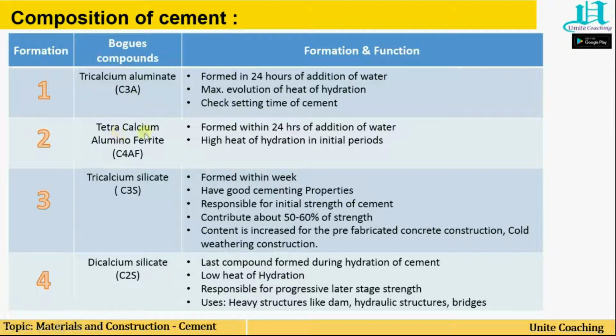Then what about tetracalcium aluminoferrite? See, it is the second compound to be formed in the cement, and it is formed within 24 hours of addition of water. And high heat of hydration is generated in the initial period because of this. Because of C4AF, high heat of hydration is generated in the initial period of the hydration process. We will see what the hydration process is. I will explain in the next slides what hydration is. But remember, this also forms within 24 hours of addition of water.